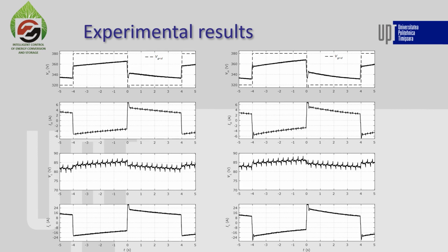If the voltage perturbations are increased to plus minus 30 volts, we observe that the charging and discharging currents are almost identical for both the conventional virtual impedance droop and the nonlinear virtual impedance droop. A special case presented here is at t equal 0 seconds, where a large voltage pulse is applied to test the reliability of both solutions.